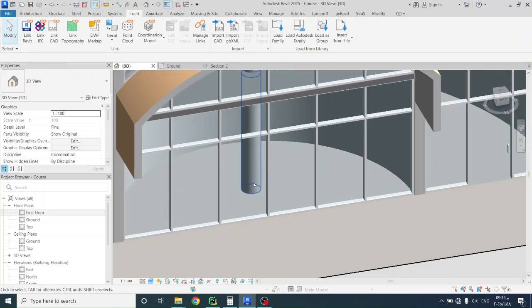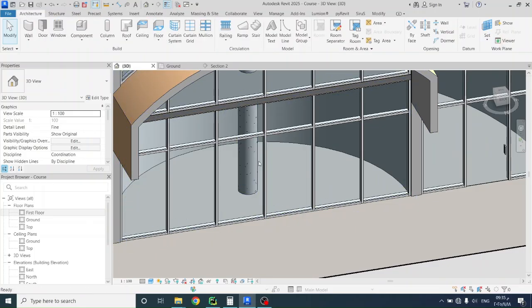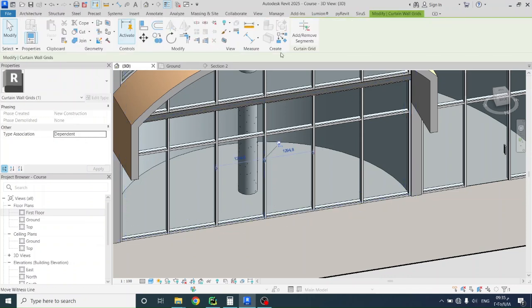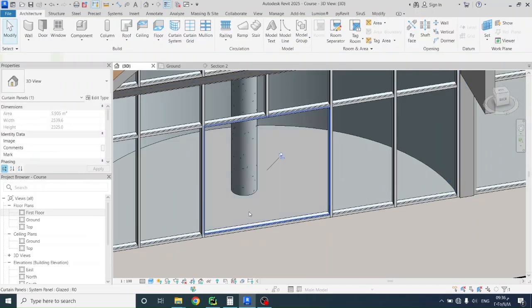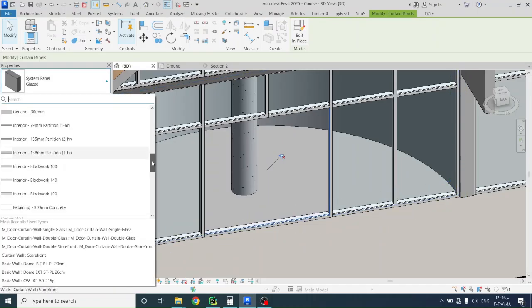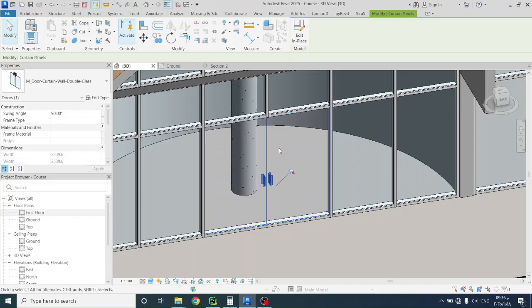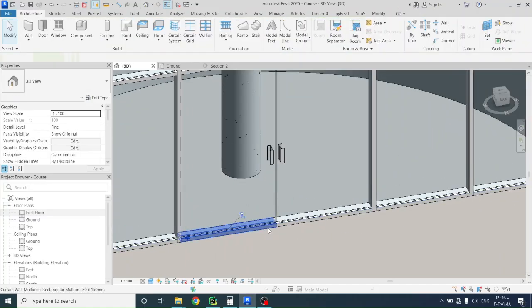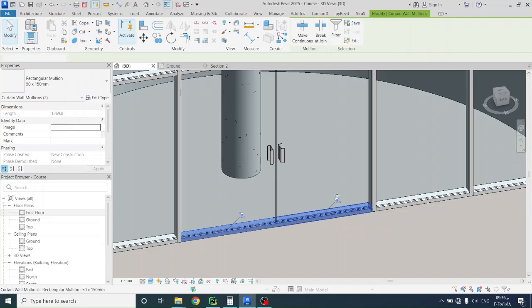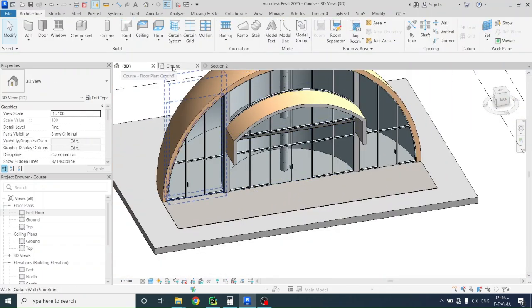And we'll do the same for the double door, the double panel here. Let's just go to architecture. No need for architecture. Select this and remove segments. Remove this segment. Nice. Let's select this panel, unpin it, and this one. This one looks good. Alright. Let's select this and this mullion. Unpin these two and then delete them. Alright, looks good enough. Let's now model the windows.